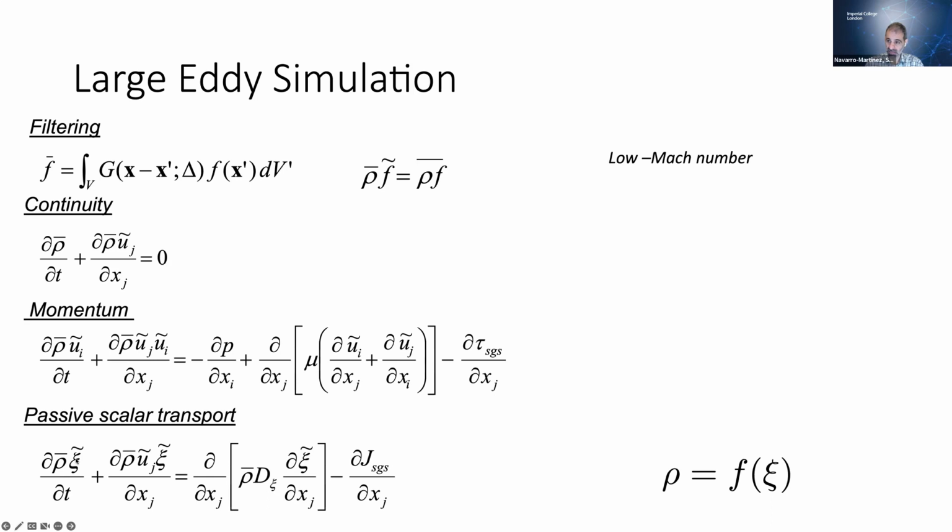This psi is this indicator that is roughly 1 at the exit of the gun, and then it disperses. The flow is turbulent, laminarizes relatively quickly. However, we still assume that all species diffuse at the same speed. This is called the unity Schmidt number approximation. This is fine because they diffuse in air. And remember, most of the species have very, very small concentrations. So everything is dominated by how nitrogen diffuses. We still have a turbulent diffusion to close.